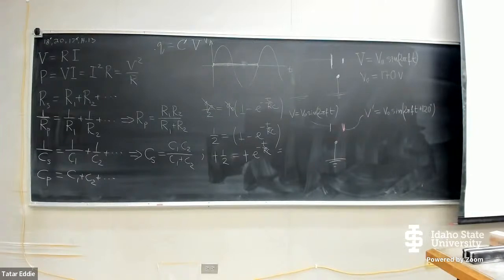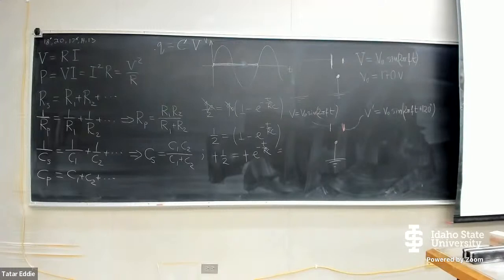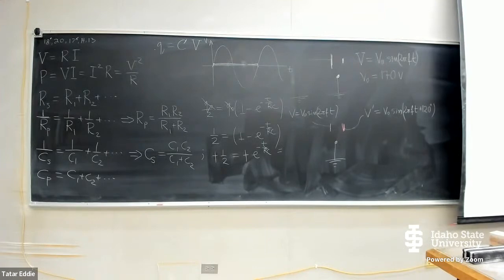Now, you don't want the voltmeter itself to affect the circuit substantially, to change the voltage that it is measuring. The way to do it is to have infinitely small current flowing through the voltmeter itself. So a good voltmeter has to have very high resistance, not to allow current to flow through it, and it has to be connected in parallel to the device across which you want to measure the voltage.